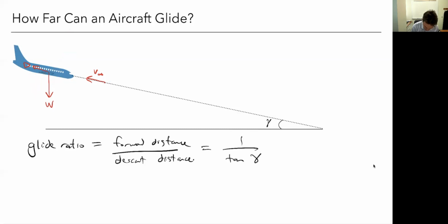Okay, so drag is that way. Lift is perpendicular, right? So this is a right angle. This is gamma. This is gamma. Okay, so I'm going to do it along those tilted axes. It'll just be more convenient. So lift has no drag component, right? Because it's perpendicular. So along this axis here, I've got a component of weight. That's going to be W cosine gamma. And then along this axis here, I've got drag equal to W sine gamma, assuming I've got steady flight.